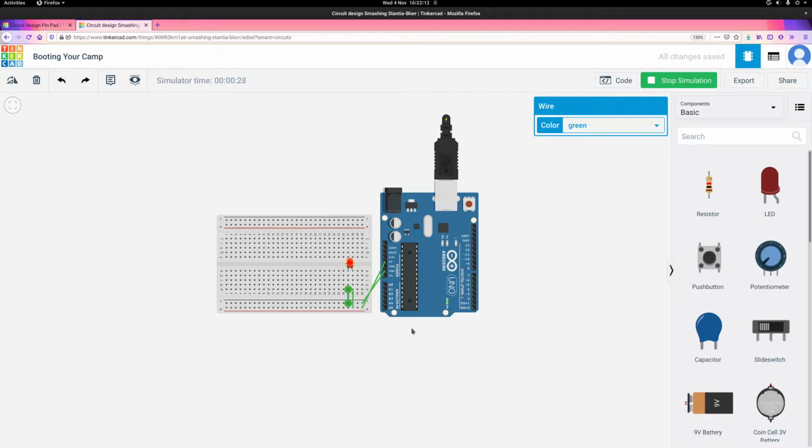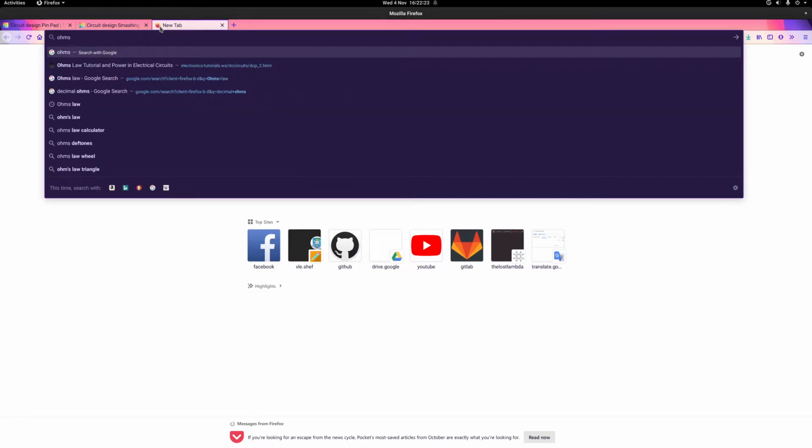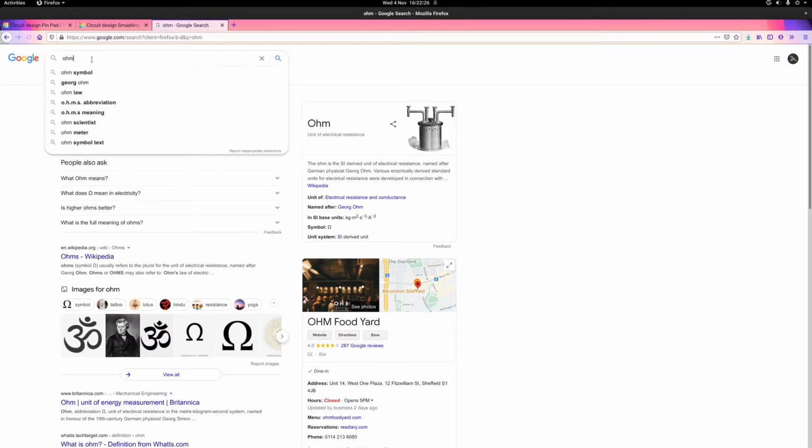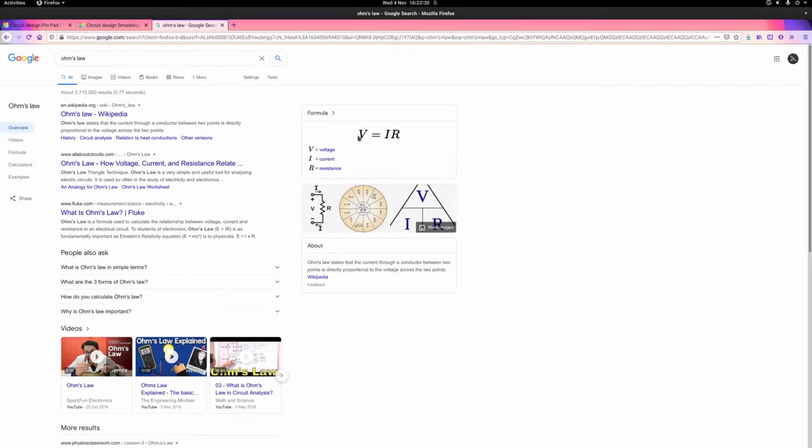to our circuit. And this resistor, if you remember from our Ohm's law, which was, I don't have a great place to type this. Well, we'll just Google it because you can see it. But it's V equals IR. Well, good job, Brooks. That was really a complete sentence. Yes, so there we are. V equals IR. So that's the equation that will help us calculate what resistance we need at 5 volts to limit the current to 20 milliamps.